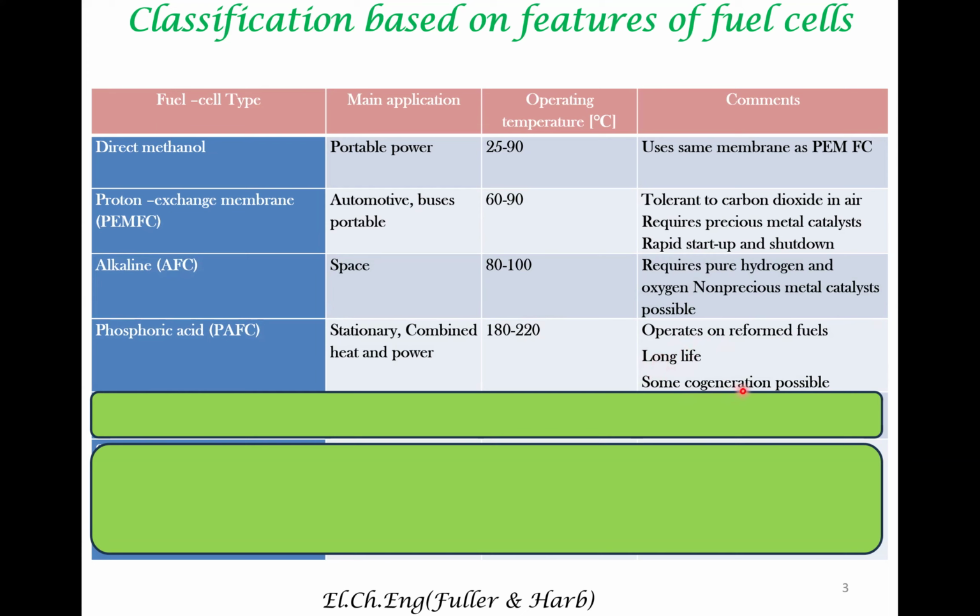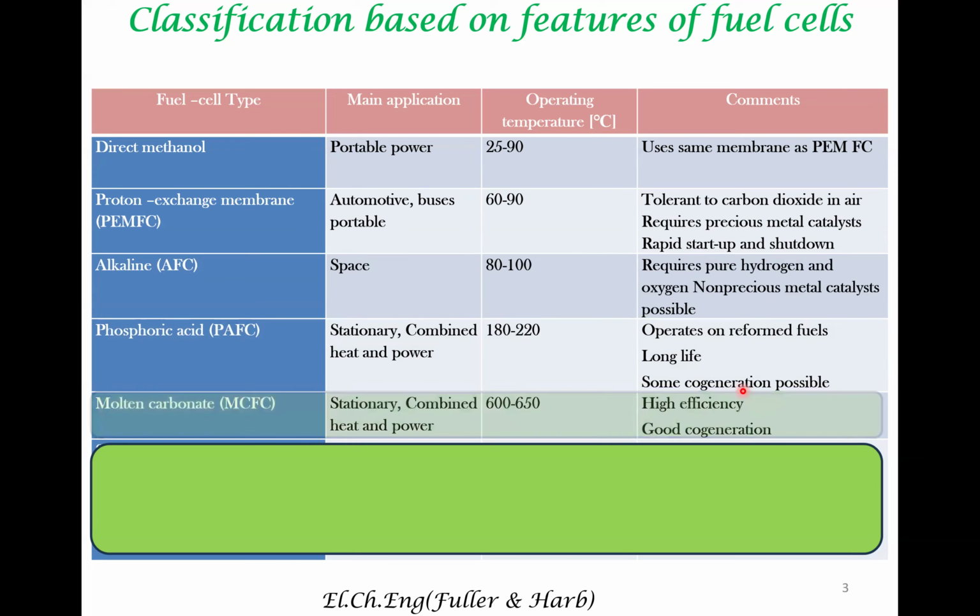What do we mean by cogeneration here is that there are two ways to generate power. Obviously, from a fuel cell, we want to get electrical power. In addition to electrical power, the exhaust of a fuel cell, let's say water vapor, can be at a high temperature that itself might be utilized for getting power, an energy conversion by thermal means. So this has been most extensively demonstrated in the context of solid oxide fuel cell. We will look at that in a minute.